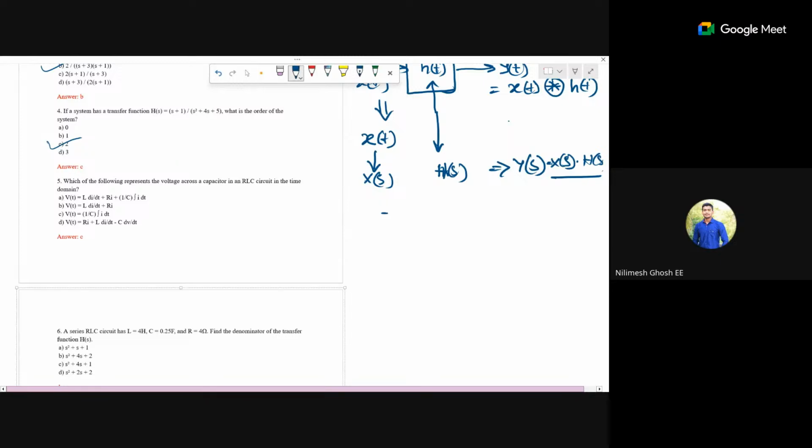Let's say we have a circuit with this C and this L, and this C. For describing the circuit, we have to assign a voltage here and also a voltage here. These are the independent voltages. These independent voltages will decide the order of the circuit. Ultimately this is the physical thing.